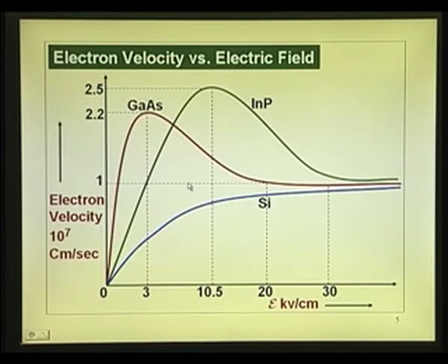Now, so we just go back to this diagram now. So, that illustrates everything. The peak electric field at which the complete transfer of electrons from the lower valley to the satellite valley is over by about 3 kV per centimeter. The transfer of electrons really begins at 3 kV per centimeter and is complete, of course, by the time you reach that point. The negative differential mobility, if you want to call it, you can call it that, because as we increase the electric field, the velocity falls. So, the negative differential mobility region is this, that is due to the electrons getting transferred onto the upper valley.